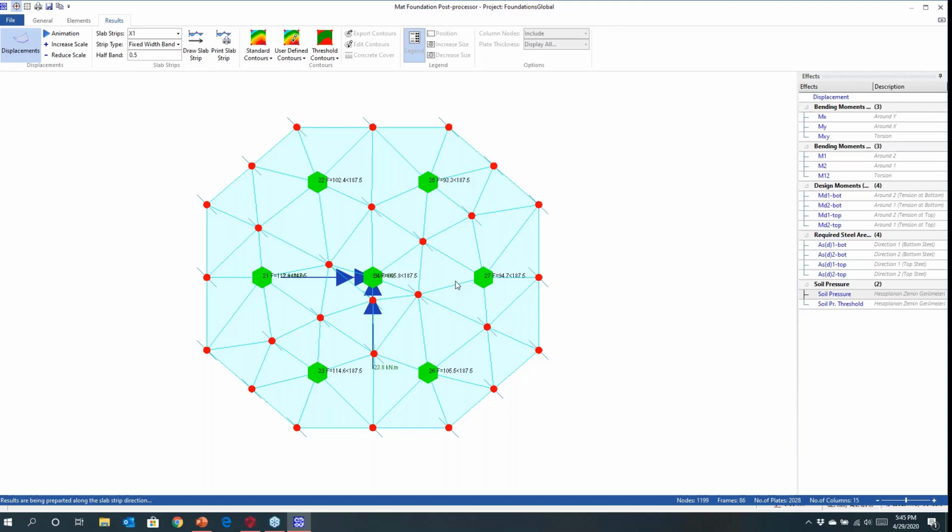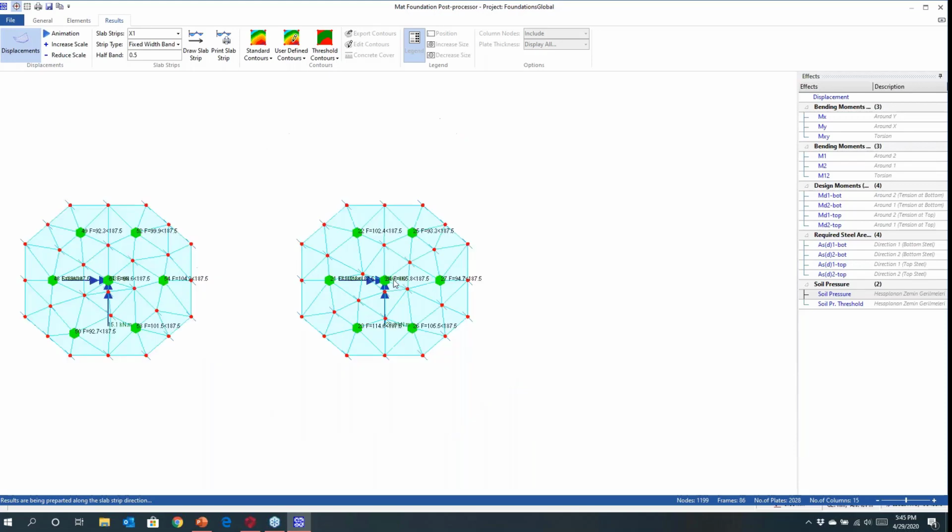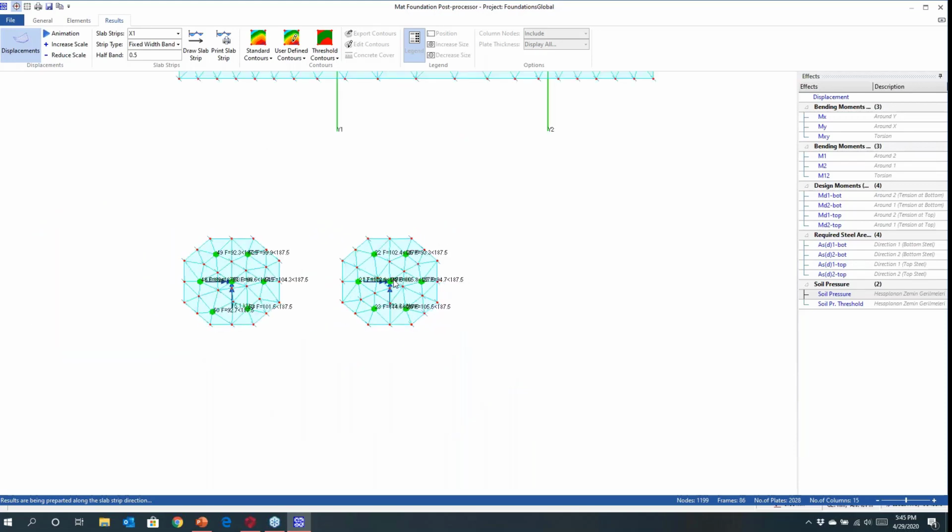Because we use rigid cap theory for the design of pile caps, and we're assuming cantilever theory, we don't typically take the finite element results. What you tend to find is with FE, if you have a column and you have a pile directly beneath that column, and then other piles may be radiating out from that, the pile beneath the column, because it's a flexible mesh, will attract more load.